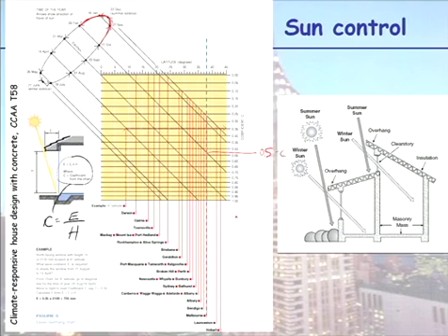So if my window is 1 metre high, I would require an awning overhang here of 0.5 metres. So that's a very simple way of telling you how far out your awning needs to be.